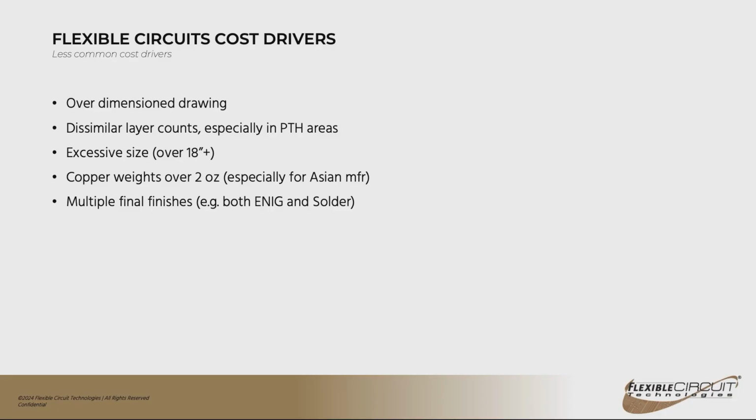If you find that you're starting to drop below that, it doesn't mean that it's not going to work. It just means that you may need to spend some time evaluating your forming methods, and you may want to talk to the manufacturer to find out the best way to form that circuit and how to handle it so you don't have problems.